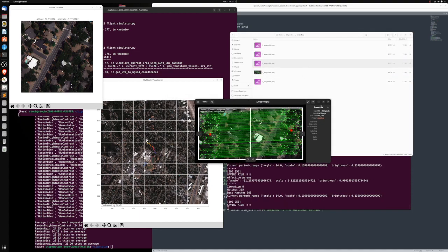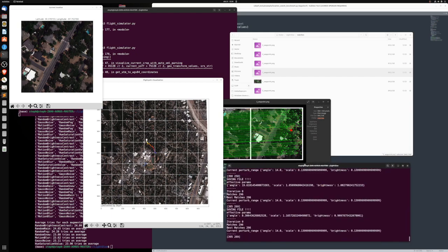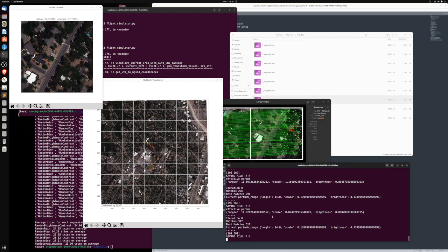Waypoint 2, this one's probably a bit better. And as you can see, it's pretty much keeping up with the flight of this drone. Occasionally, so what it's doing is actually based on momentum of the previous movement. It's estimating what the next tile should be for the search. And so it's doing a pretty good job of keeping up here. As you can see, it's keeping up when it only does one search per image. And when it only does one search per image, it's insanely fast.